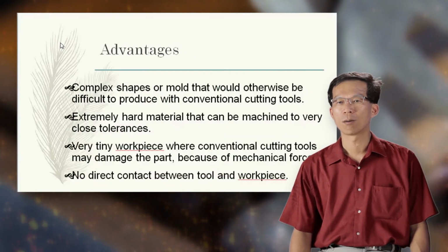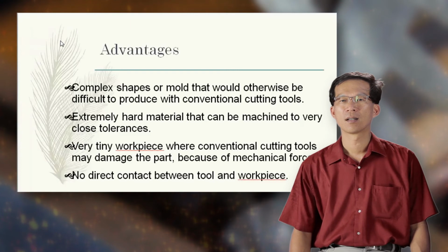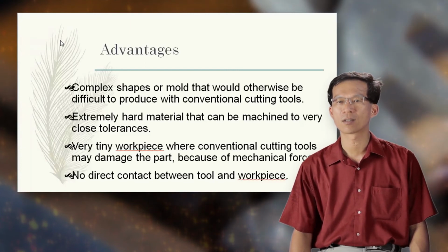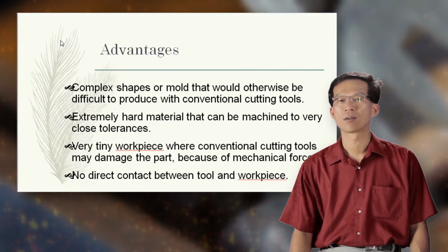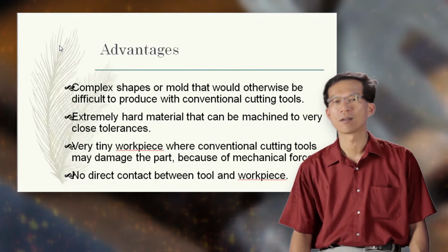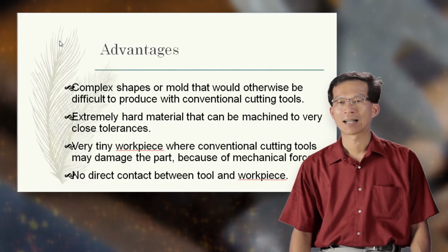The advantages of micro-EDM are complex shapes or molds that would otherwise be difficult to produce with conventional cutting tools; extremely hard materials that can be machined to very close tolerance; very tiny workpieces where conventional cutting tools may damage the part because of mechanical force; and no direct contact between tool and workpiece.